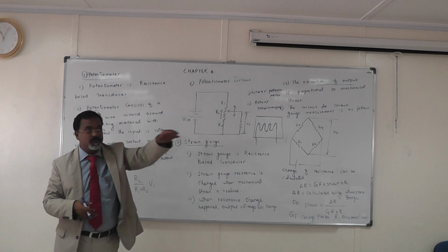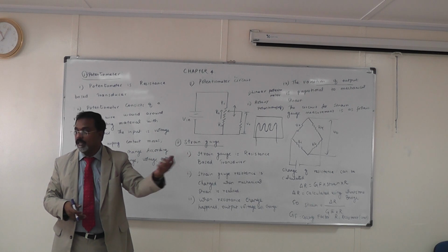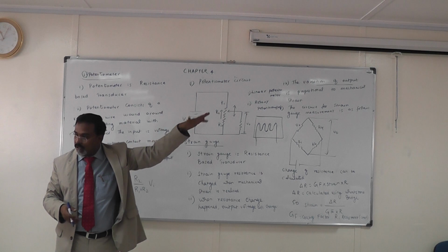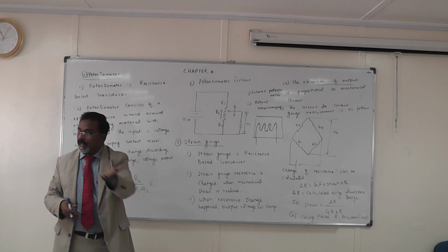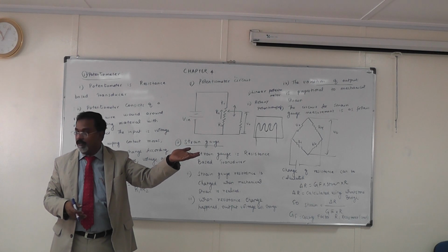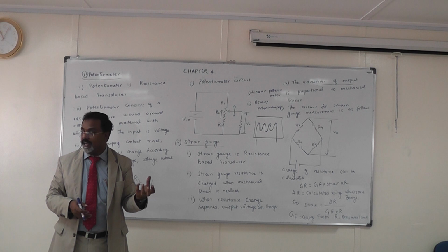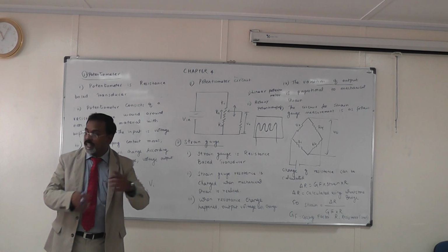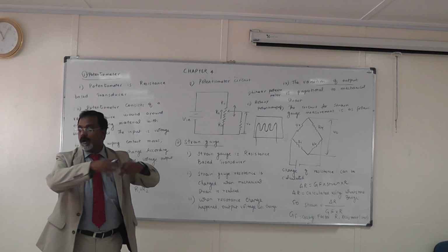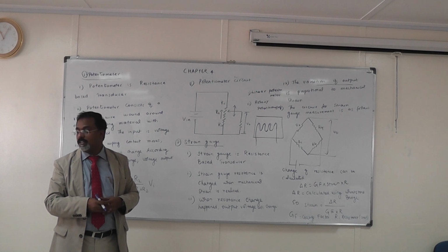See the deflection of the bridge. If you want to find it, you can place different strain gauges in different places, and then when some load is applied on the bridge, automatically what will happen? This bridge will deflect. So if you want to find how much the deflection is, you can use these strain gauges. How much the variation is, you can equate with the deflection, so you can find the deflection of one beam or bridge, a simply supported beam, all those things, using these strain gauges.